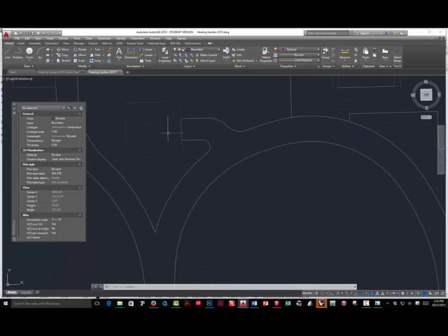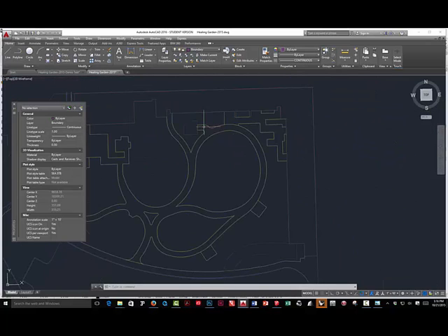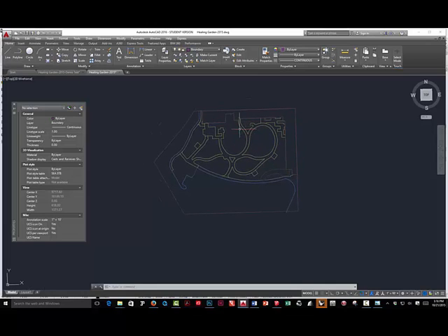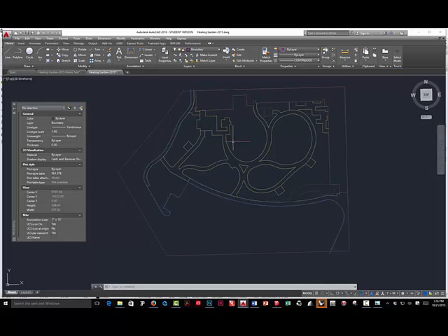So again, it comes down to how good your AutoCAD drawings are. If they're well done and you isolate and clean them up, that works pretty well. So for this information, this looks pretty good. Now I could pull the contours in here and do this export all at the same time. Since the contours have elevations, they won't come in connected to this geometry. But since I have this separate, let's just do it separate. And then we'll isolate the contours and export that.